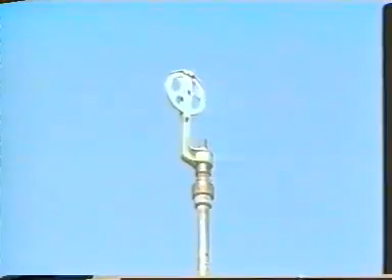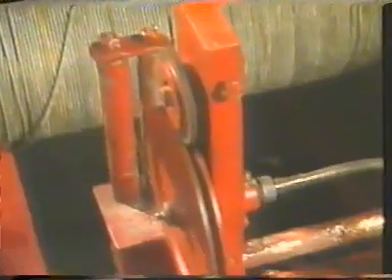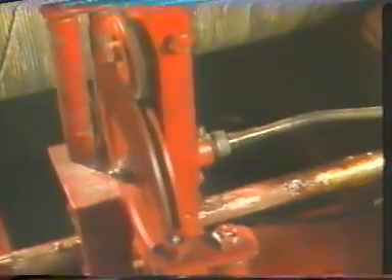When exceptional strength is required, a braided wire line is used at low pressure situations. However, there are other factors that affect the strength of the wire line. When wire line is run into the well, it must make a number of bends as it comes off the reel and makes its way to the well. This bending of the wire line tends to take its toll over time and causes the wire line to become work hardened. So wire that has been worked is not as strong as wire that is new.